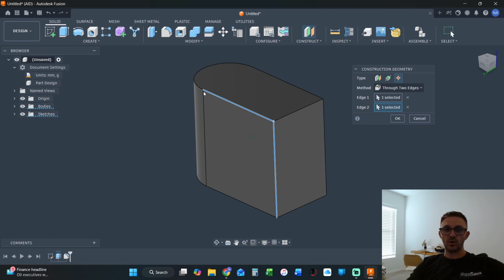So basically, we're going to define a point somewhere along this line. And then by selecting this line, we're saying, okay, it's intersecting this line at this location. That's where I want the point. That's essentially all Fusion is asking for, is where do I drop this point? And that's how you're going to define it to Fusion, or any CAD package for that matter.